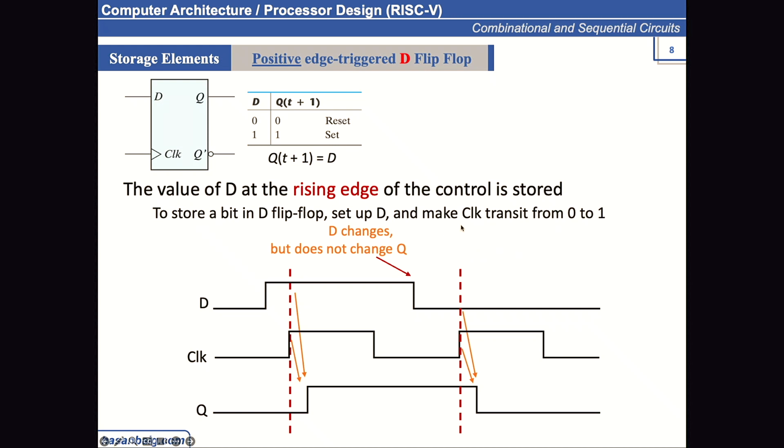So this is how, first of all, the activities in a computer are synchronized because of these clock edges, positive clock edge. It's up to the designer also. They can make the circuit synchronize either on the positive edge of the clock or the negative edge of the clock. Okay, but the entire circuit should work on the same clock edge. Some more complex circuits work independently on different clock edges.